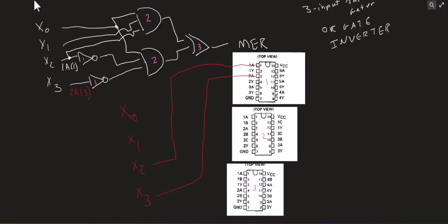And the pink 1 on here tells me it's with chip 1. And then the output from 1A is 1Y. So that's 1Y. And then I'll put in parentheses that that's pin 2, so I know how to connect it on the breadboard. And the output for 2A is 2Y. And that's pin 4. So I know how to connect those onto the chips on the breadboard.